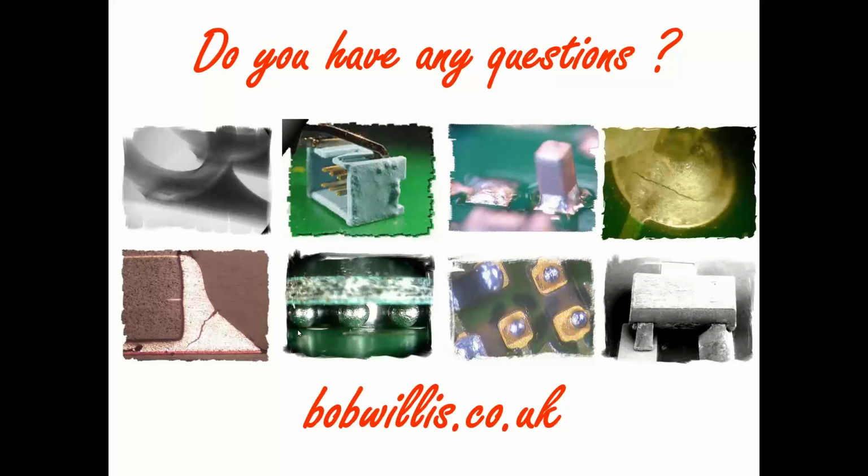Okay, just a comment again. When brushing, go slower, allow the material to flow. Yes, but the point I was trying to make is that if you change the solids content, the viscosity of the material, you will find it better to assist you if you are going to use a brushing technique. But generally speaking, I would only use a brushing technique for rework and repair rather than actually in the manufacturing process. But it's a good point.